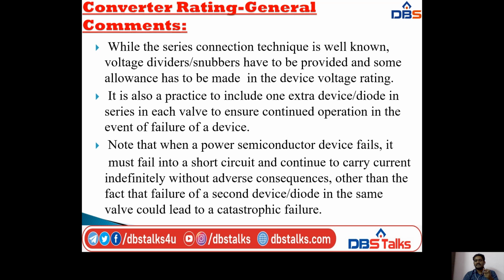So note that when a power semiconductor device fails, it must fail into a short circuit and continue to carry current indefinitely without adverse consequences, other than the fact that failure of a second device or diode in the same valve could lead to a catastrophe.